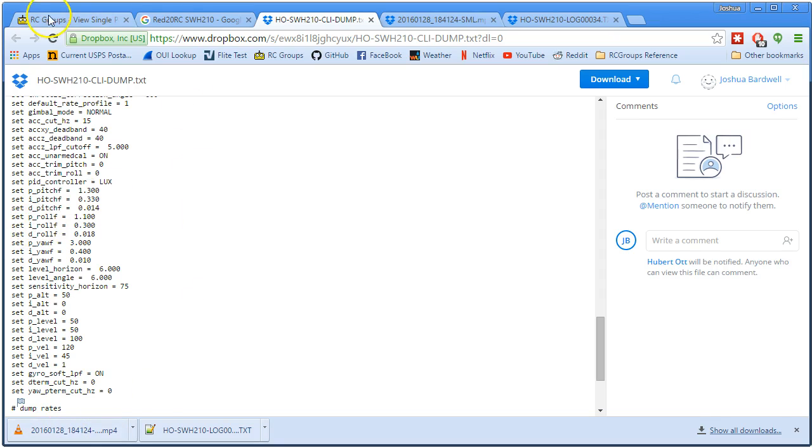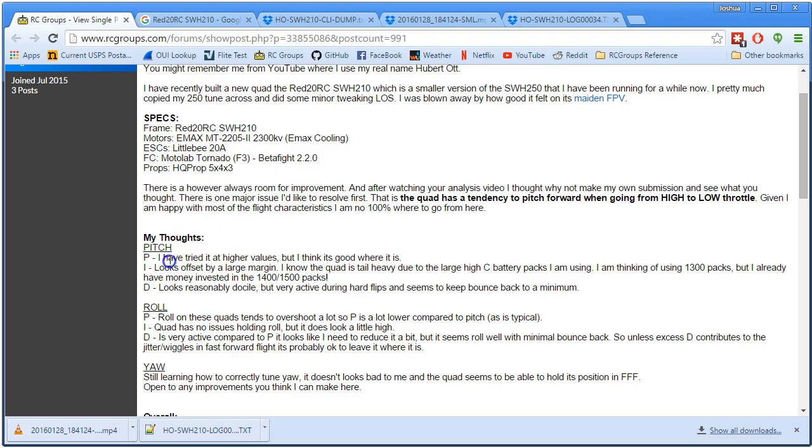Now, you sent me a bunch of other information. You've tried it at higher values, but I think it's good where it is. Well, I think it should be higher. I think this problem is... See, here's the thing. What can you do to fix this problem? Well, you can raise I gain, and I will respond more quickly, and that may help, actually, because your I gain is a little low. So if you really are resistant to raising P, then raise I to like 55.